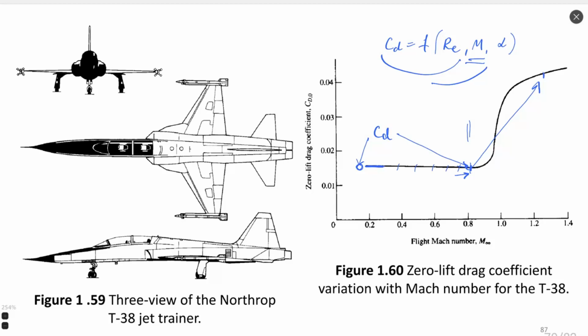We can reduce the number of numerical simulations significantly when we would like to find the drag coefficient, and find the drag or required thrust of our airplane. We provide just one test or one simulation at conditions we are interested in, or where it's easier for us, and we can say that in all this region from 0 to transonic the drag coefficient will have the absolutely same value.